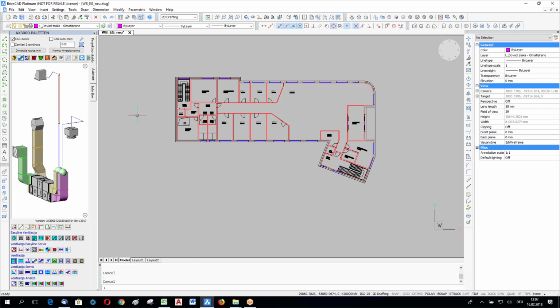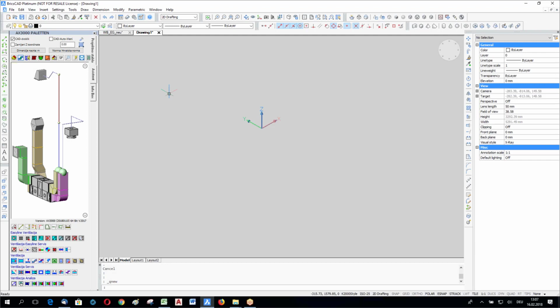Then it can be used variably in any size. We use standard AutoCAD blocks, so I start with an empty drawing inside the plan view, and I draw lines. So I draw the graphic of my block, only a square with the size of 1.